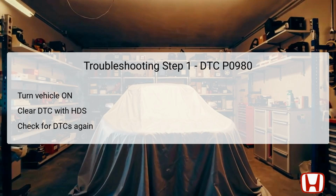This process allows the system to reinitiate its self-diagnostic routine, and the technician should again check for any pending or confirmed DTCs using the HDS. The goal here is to determine if the fault is persistent or if it was an intermittent issue, which can provide key insights into further troubleshooting pathways.